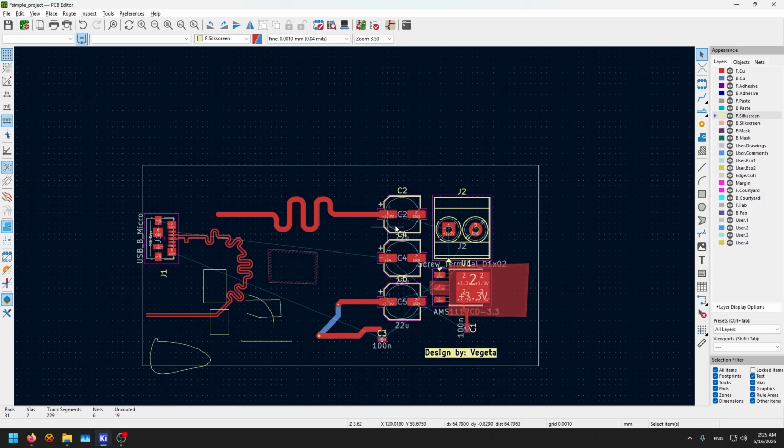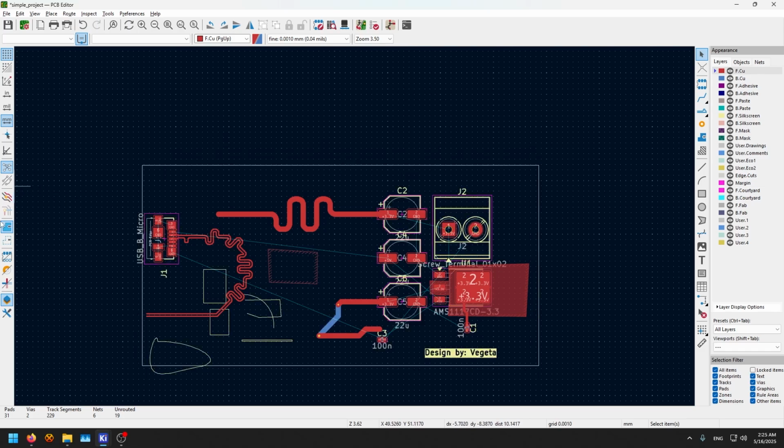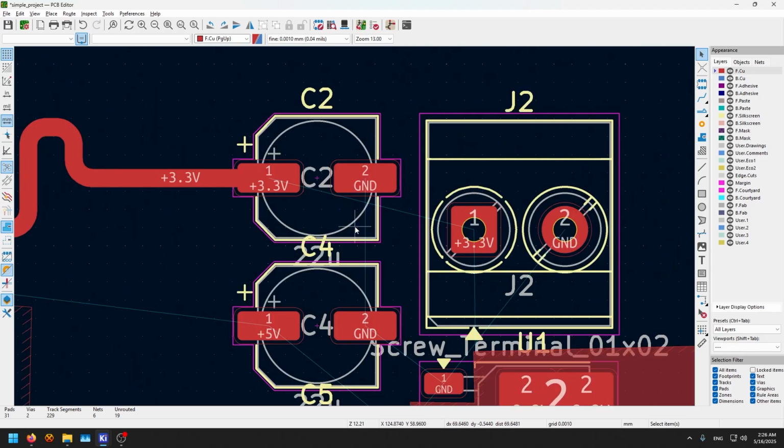This makes the inactive layer dim. For example, like this. Now I am active on the top layer. I want everything to be dim. And here are the draw zone, either drawn or not drawn. No, I want them to be fully drawn so I can know which one is poured and which one is not. And here basically the same thing for the pads and the vias. Look at this for the vias. Draw them or not draw them. The pads, let's go to the pads.